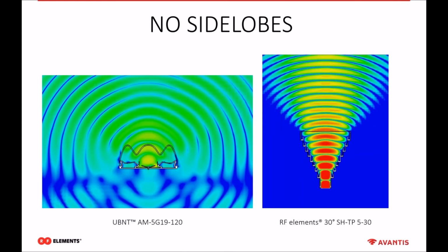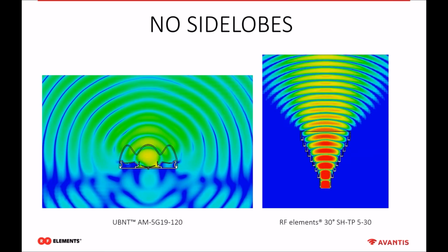And as you can see, symmetrical sector antennas do not have any side lobe, so the signal is radiated into the main lobe, the direction where you want to have a signal. This is because of the type of the antenna. The type of the symmetrical sector antenna is called a scalar horn. The beam is highly focused to achieve better performance from an RF point of view.